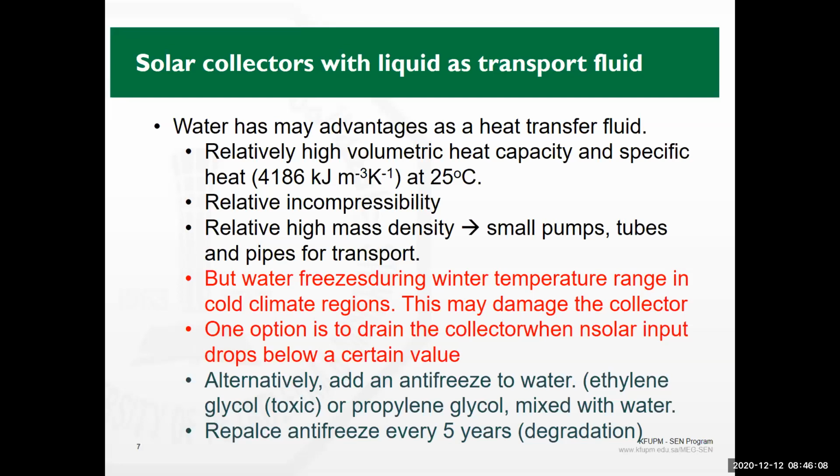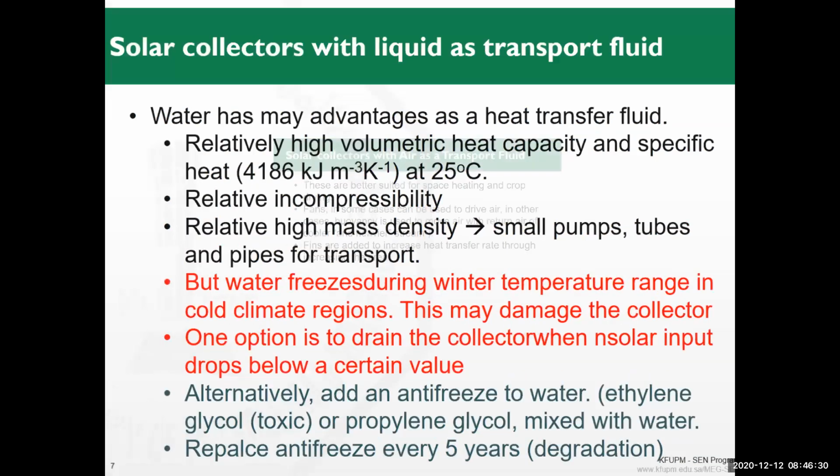So the water is stored in a tank. And whenever the solar radiation is a little bit higher or the sun is up, then you can recirculate your water again. The antifreeze has a lifetime of about 5 years, after which it should be replaced. Otherwise, its chemical stability is going to be affected.